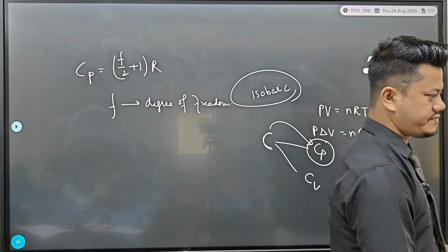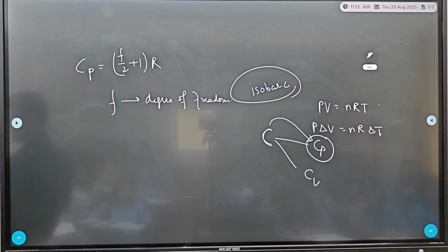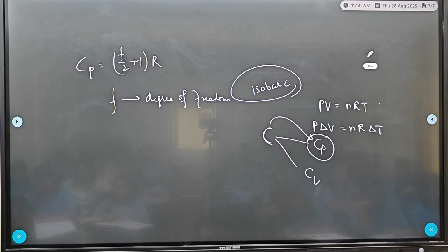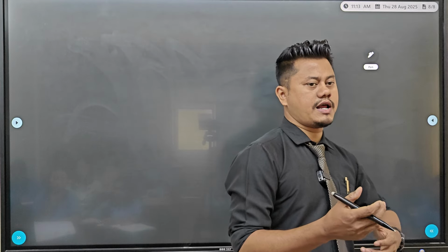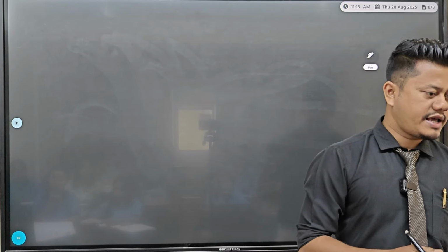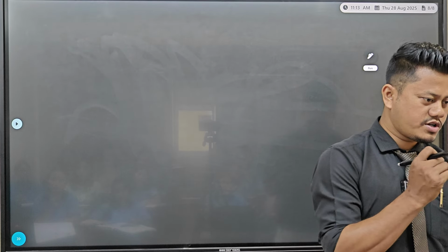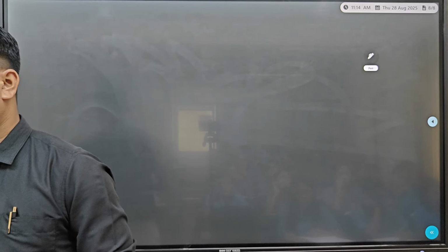modulus of elasticity. Got it? In terms of constant pressure. Just write modulus of elasticity. Got it? Modulus of elasticity. Now what type of modulus of elasticity we need to use here? Since we are dealing with gas, understood or not, we need to use bulk modulus. Got it? I cannot use the Young's modulus. Young's modulus will be in terms of length. The strain needs to be longitudinal strain, right? Since gas has got volume, I'm going to use what? Bulk modulus. Is that clear?